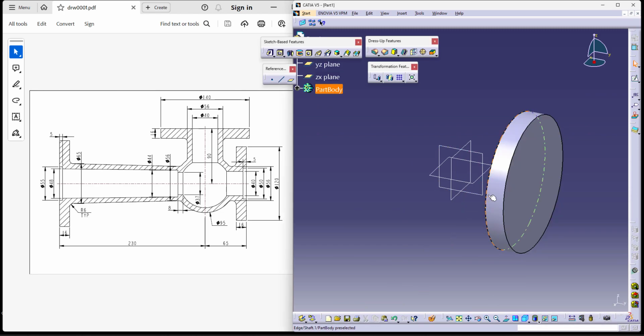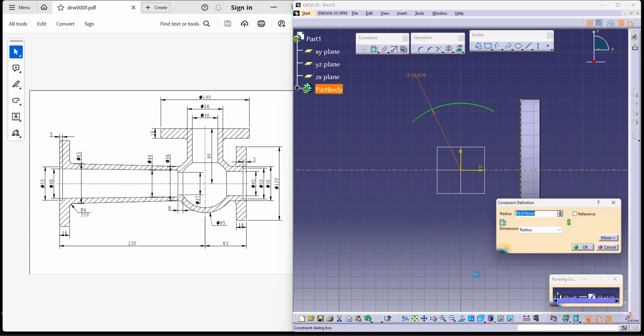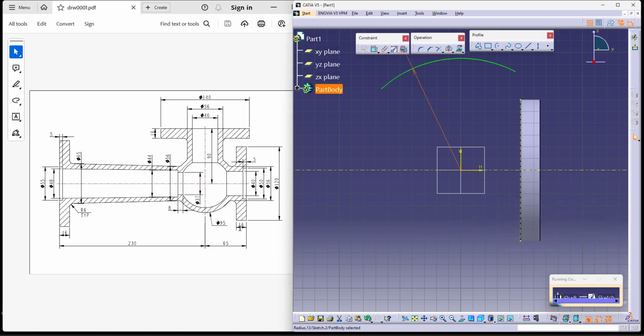With my reference of this cylinder, I'd like to make the complete rest of the shaft. So using my shaft again, I'm using this as my reference. Let us select the axis as usual as well as our edge reference, which I'll be using to make the model. I can directly use a profile command, but before that let me try to create a simple 95 diameter circle so it won't create an issue later on. This is your diameter, this is your 95. As you can see, this is the 95.